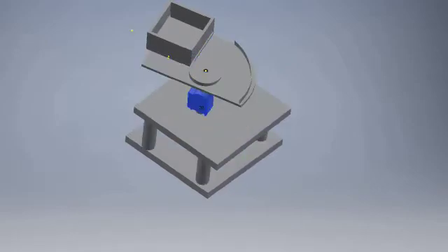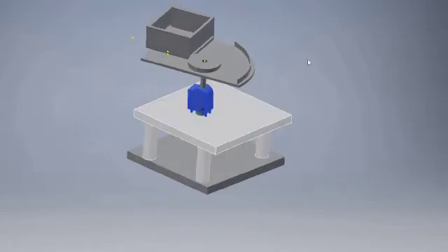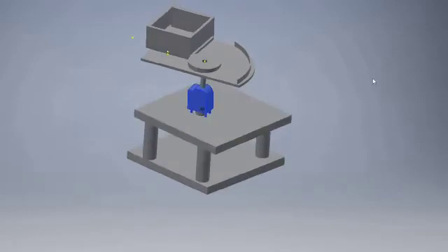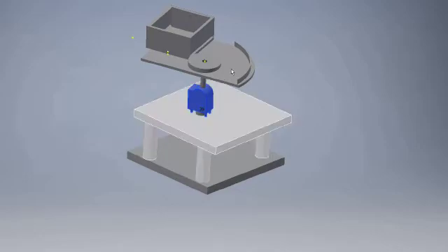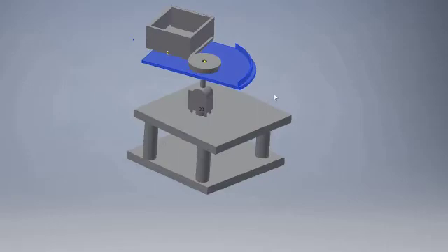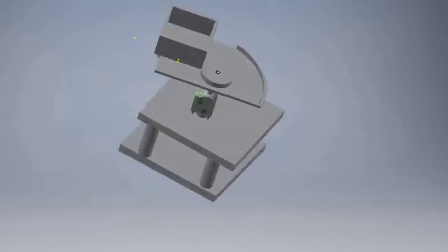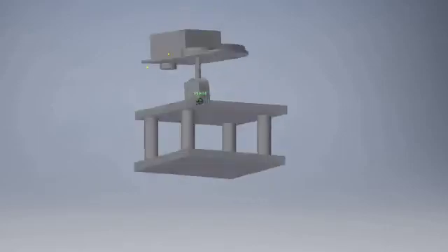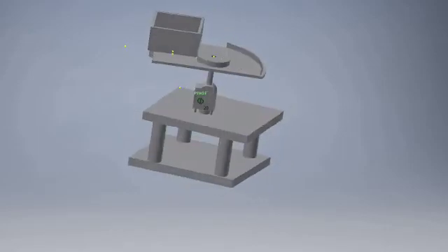Now the third part is the aiming unit, which consists of a pan tilt servo system. This pan tilt servo system will be powered by an Arduino Mega 2560, and under that pan tilt servo system, a servo motor is mounted to control the direction of this launching hub horizontally as well as vertically. This will help our disc to aim at a particular angle. So these were the 3 main important units.